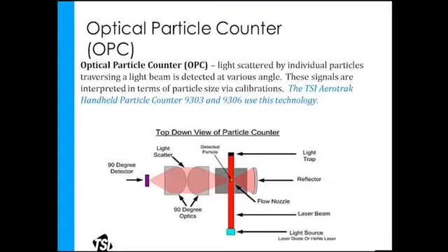Optical particle counter, again, is pulling air through a chamber, and the optics are a little different because an optical particle counter is literally counting the number of particles, and it's sorting how bright it is. The brightness will be associated with the size, so it's going to keep track of how many or how bright. So again, this is kind of the simplistic 5th grade version of it because I don't know technically how it really can do it. But there's different angles of measurement and the photodetector is a little bit different in this than in the photometer. So it's measuring particles and it's counting them by size and puts them in different bins.